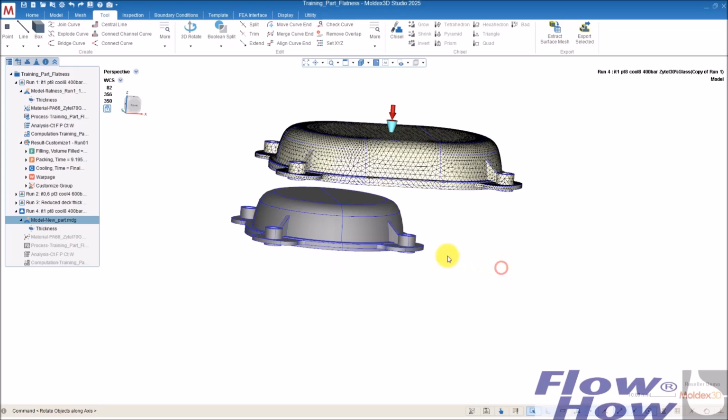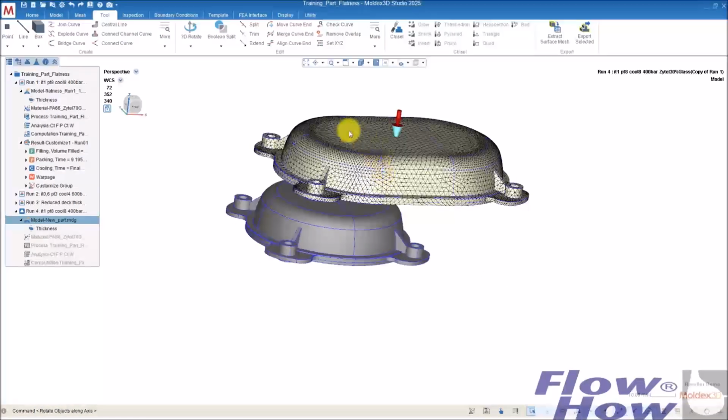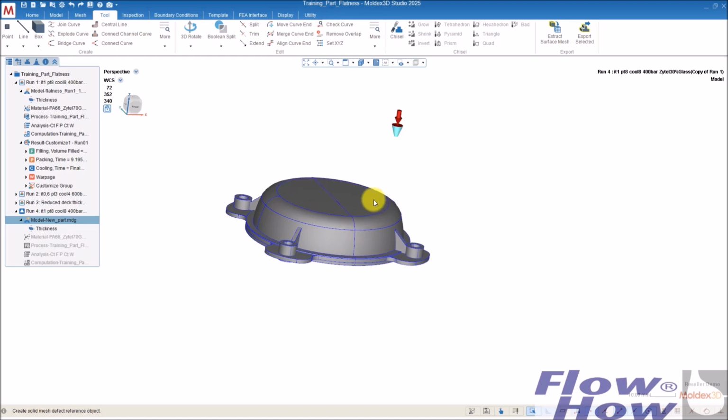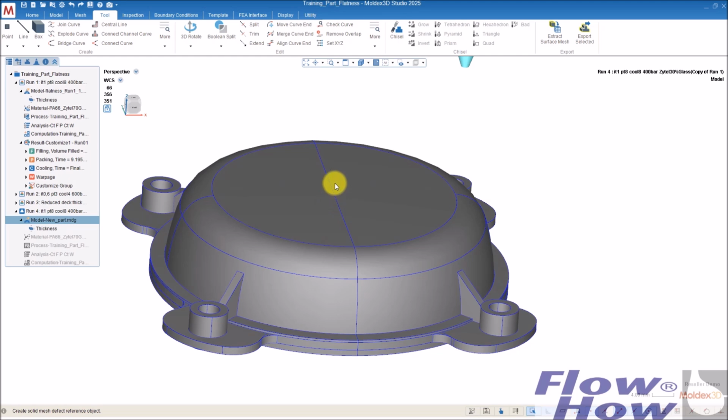Now it's correct here, but I need it to be moved up here, so I take this one, and then I want to catch the midpoint, or the center of this, and move it to the end point of that. So look here, move is gone because the latest action I had was the rotate, so I have to find move down here.